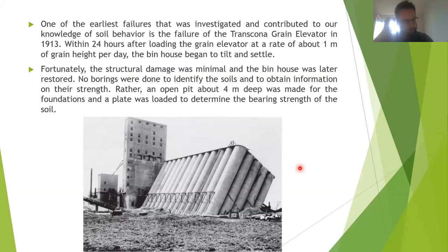For example, if you have natrium-rich soils, then they are usually swelling soils. And the problem with swelling soils, of course, is that they swell, and you need to overcome that swelling pressure. Basically, last year I worked on one design related to swelling soils. We had a swelling pressure that was like 20 tons a meter.